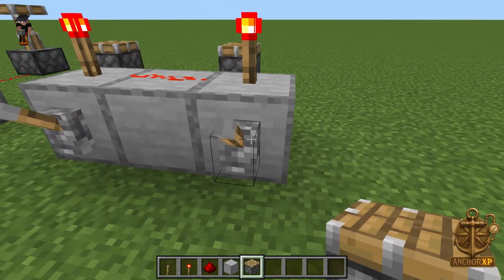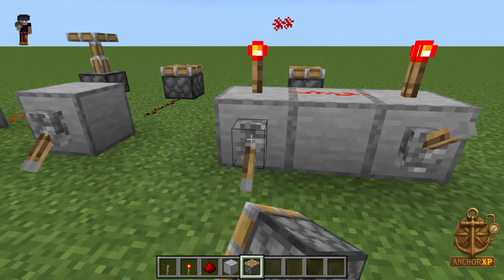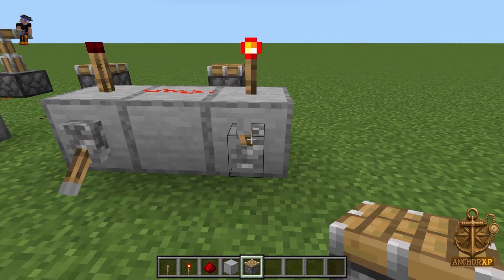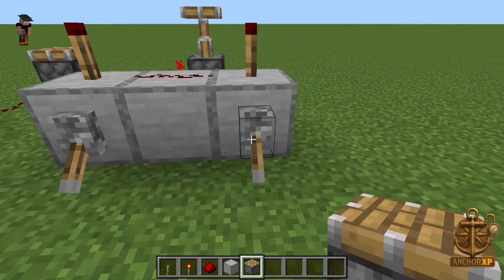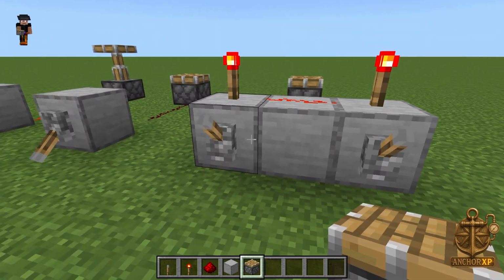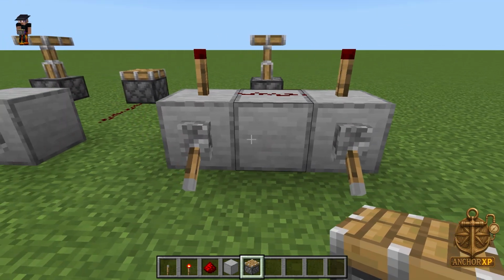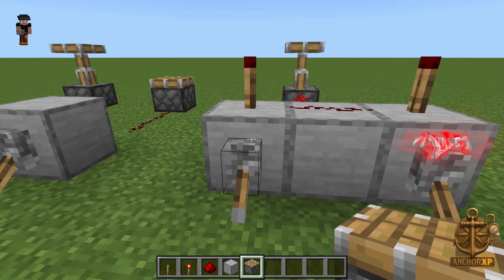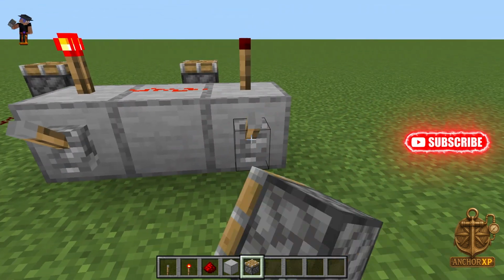And then now when we flip the switch, if one is on, nothing will happen. However, if I turn both off, then the piston gets activated. So this requires both to be in the off position, hence the term AND. This and this need to be together.